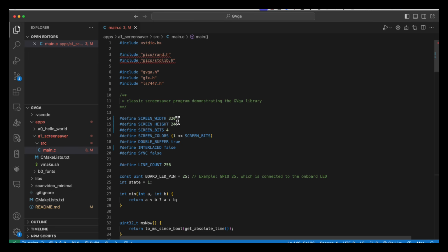So now we want to demonstrate what I would call mixed mode graphic resolutions. So normally we do 320 by 240 or a multiple of that, 640 by 480. But what if we said only 200 pixels here? That would cause the VGA engine to have too few lines to scan. So what we do is we pad the top and the bottom with enough pixels to create 240 total. The other thing that we do, if we go past the median, so normally 240 is what we would put here, and what if we went to 360?